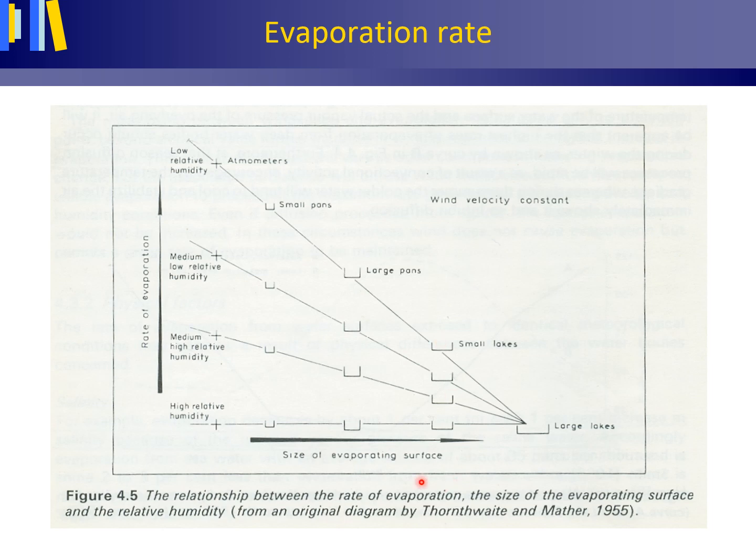When the weather is warm and the relative humidity of the air is low, the difference between pan evaporation and open water evaporation will be larger than when the weather is cold and the relative humidity of the air is high. Thus, pan coefficients for the same type of pan are usually smaller, that is, a larger correction is needed in summer than in winter.